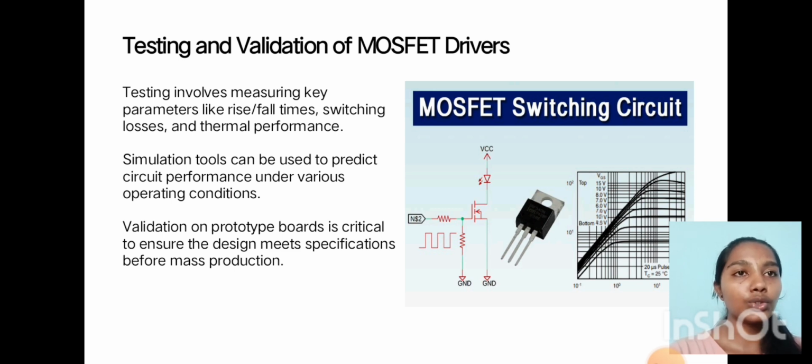Testing and validation of MOSFET drivers. Testing involves measuring key parameters like rise and fall times, switching losses, and thermal performance. Simulation tools can be used to predict circuit performance under various operating conditions. Validation on prototype boards is critical to ensure the design meets specifications before mass production.